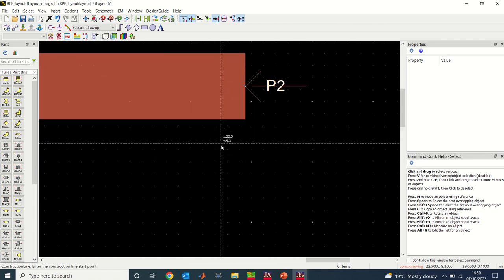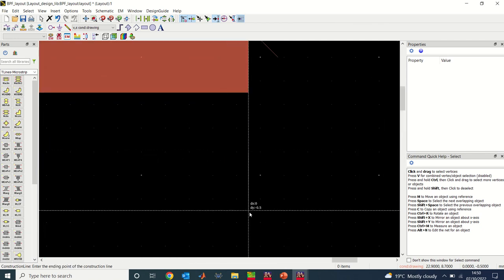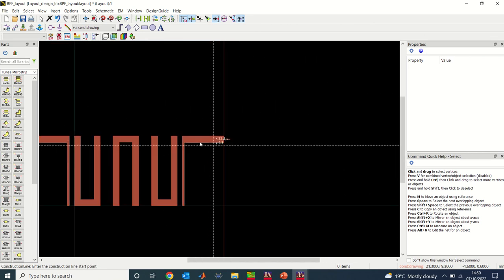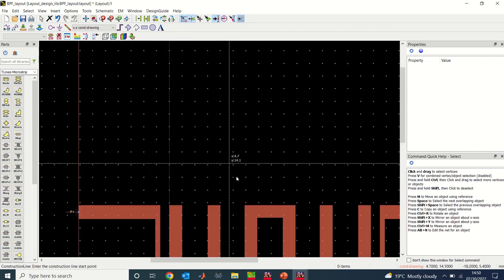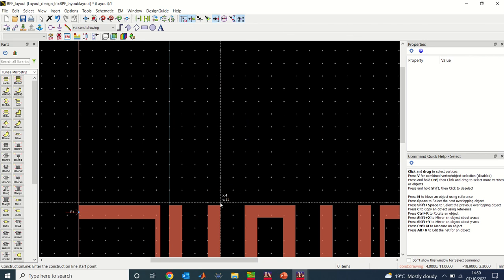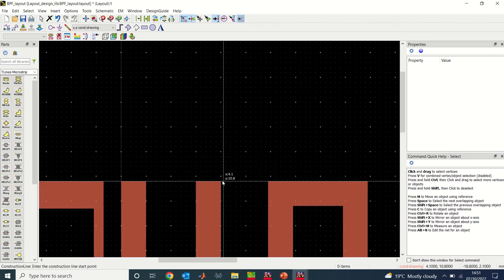Do the same here. Click once, 2. All right. That's good. Now we want 6 millimeters. We know that each of these red square is 1 millimeter. If you're not sure of that, you can see when we touch this. So that point to that point, 1 millimeter. Another way to do it is you can just look at this. You see now your y-axis shows you 10.8.